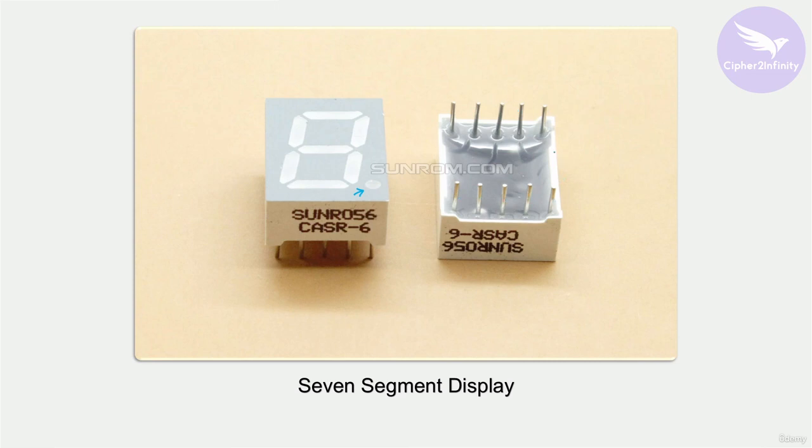There are 10 pins here, and there are 7 LEDs and an 8th LED for the dot. So there are 2 extra pins here, and those 2 extra pins are for the ground. You will get that in a moment. First of all, let me show you the pin configuration of this 7-segment LED display, and from that you will get more clarity about this SSD. So let's see the pin configuration now.